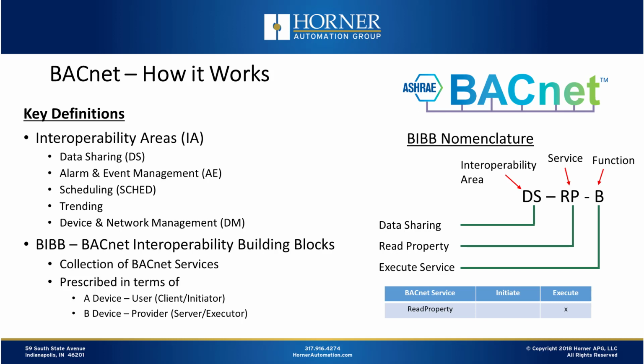And then that concept is also used hand in hand with what's called a BIB, a BACnet interoperability building block. That is a collection of BACnet services. And those are prescribed in terms of whether that service is being utilized by a device where they are a user or a client, or whether they are a provider or a server in that particular case. And these are abbreviated.